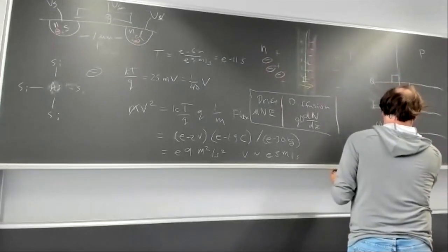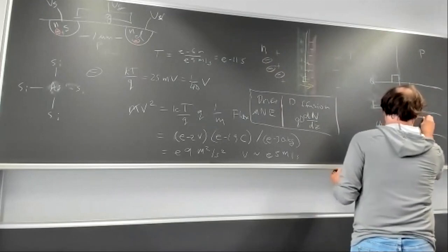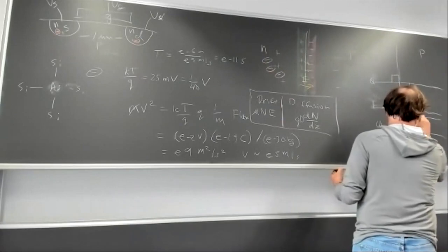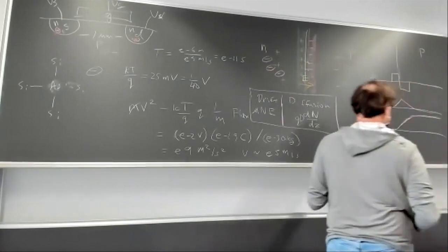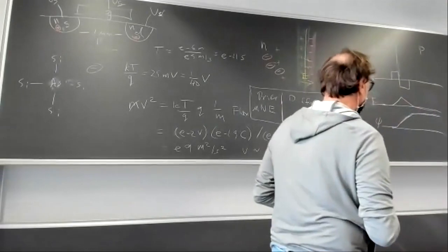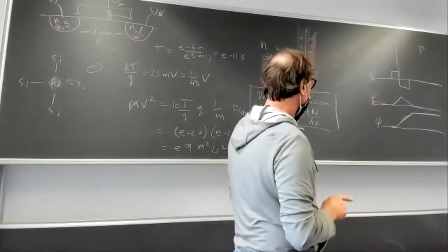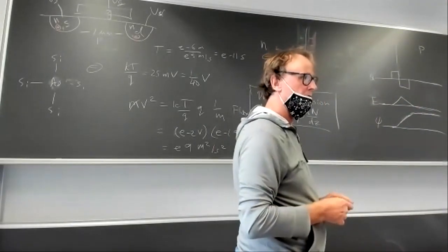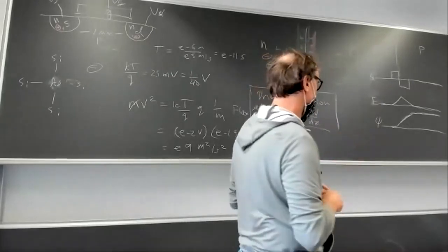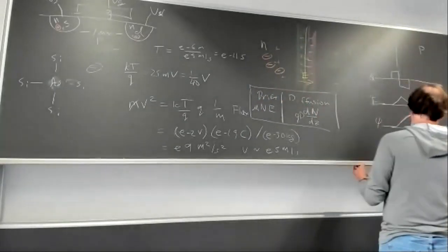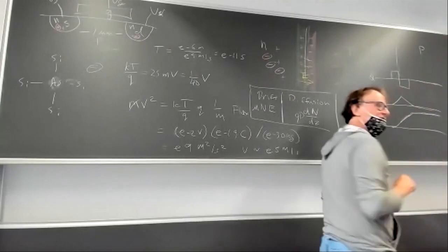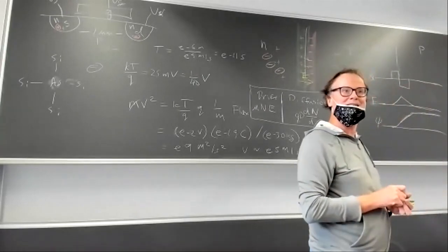And that looks like the integral of this triangle, which is, well, I'm not going to draw this properly. It's just something that looks like two parabolas. The integral of a line is a square function. And so that builds up a voltage between these two, actually a potential between these two N and P regions. And that potential is, anybody know roughly what it is?